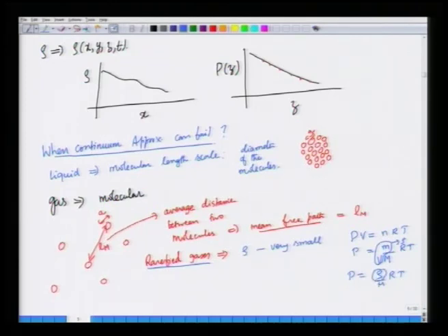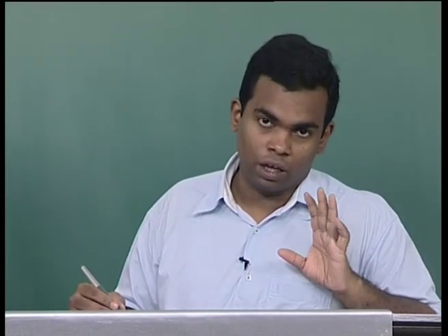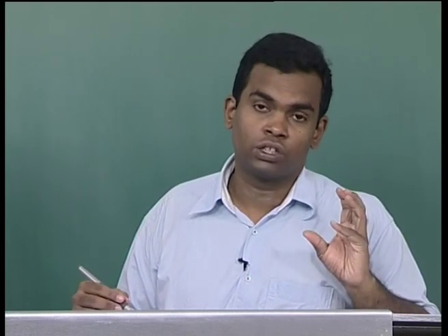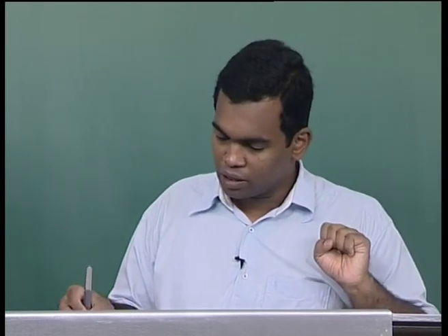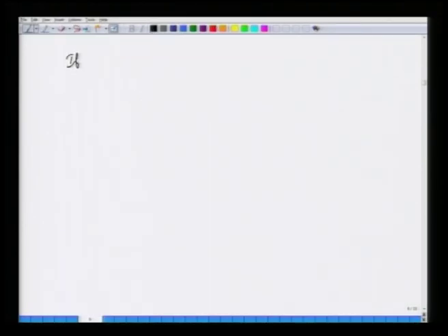So, when can you get low densities? When the pressures are low, that means the density is low, because pressure is directly proportional to density in a gas. These conditions are encountered in some applications, when the pressure is so low that the density becomes very, very small, then the mean free path becomes large. By very large we mean that the mean free path becomes comparable to the macroscopic dimensions.